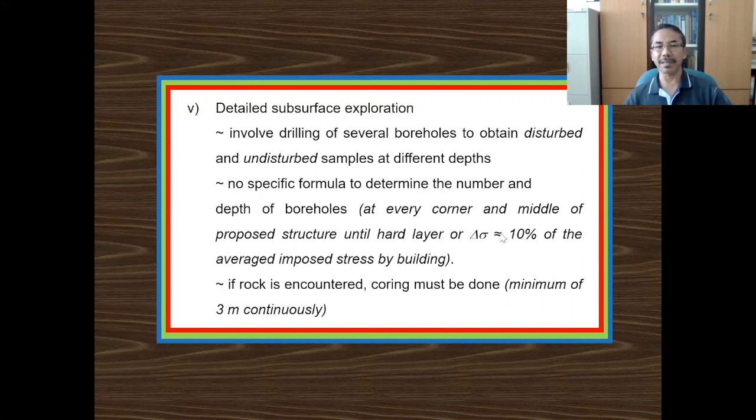There are several methods that you can employ to obtain the depth at which the stress increase is about 10%. You may use a simple method, or some people call it the 2-1 method, or other methods, whichever you are comfortable with. So those are the approaches.